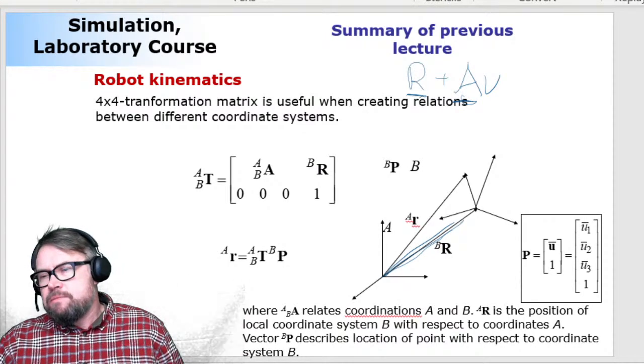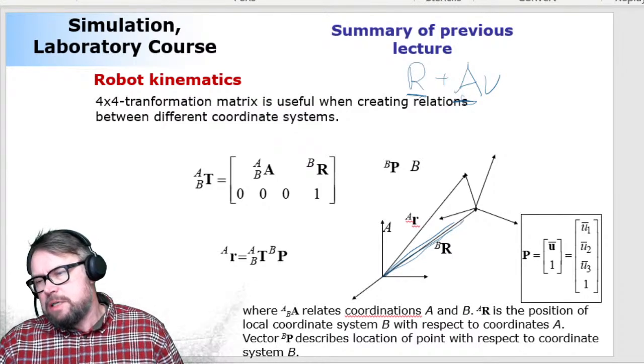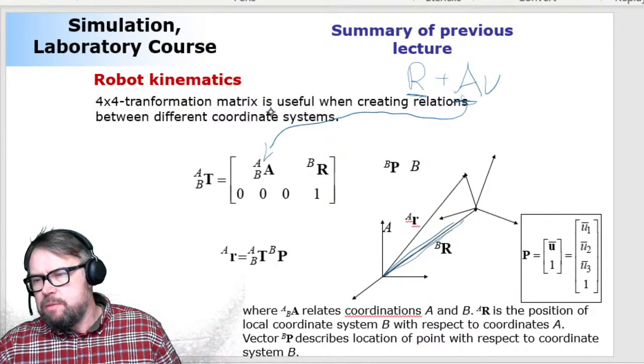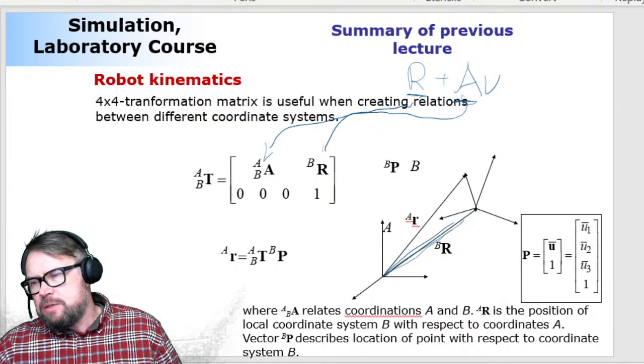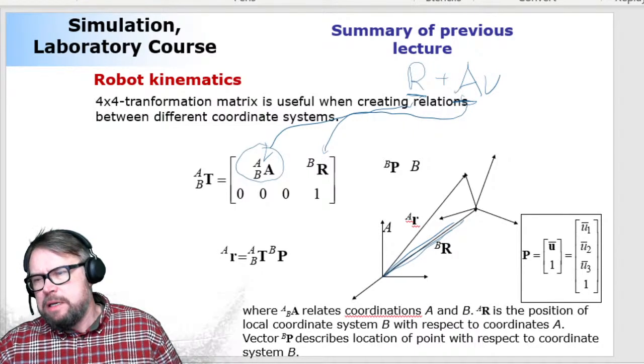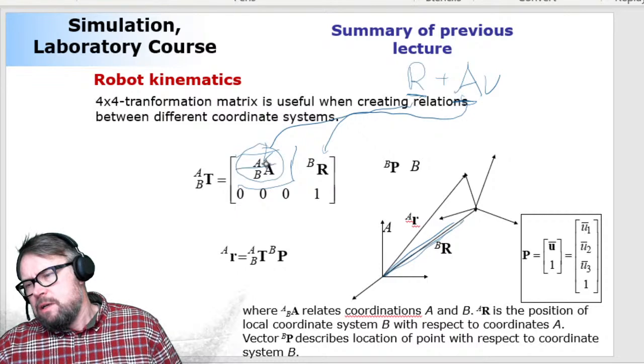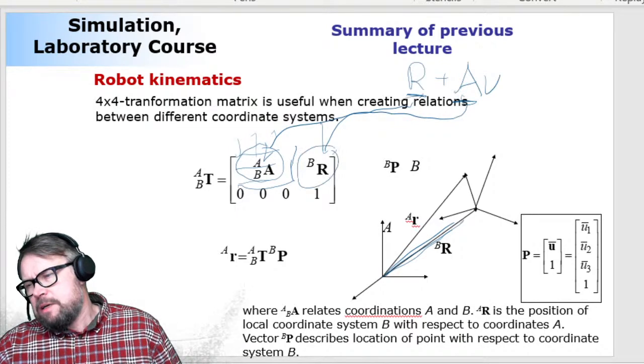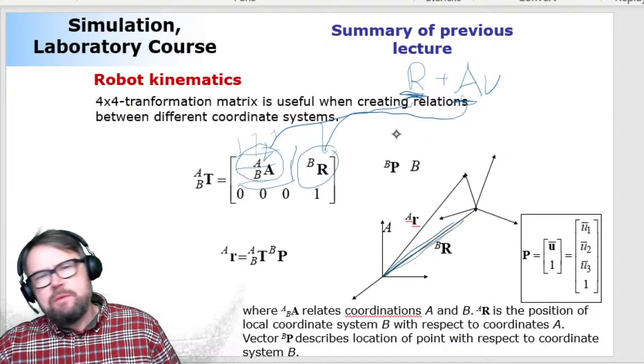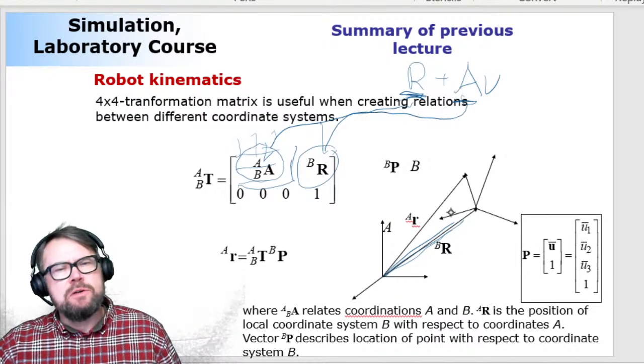And what you do in a 4x4 matrix representation is that you simply relocate these components into a 4x4 matrix. It goes such that the rotation matrix goes in the upper left corner. So it occupies the first 3 rows and corresponding columns. And then the final column here will be the translation of this guy. This vector R will be simply relocated to the new location.